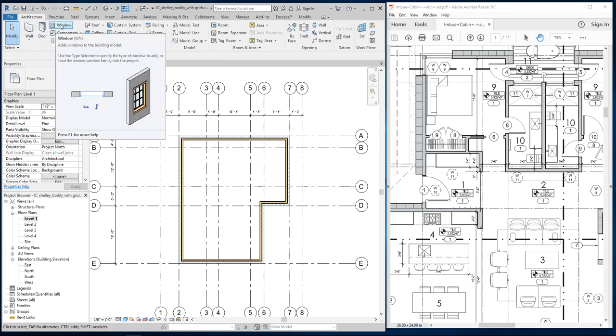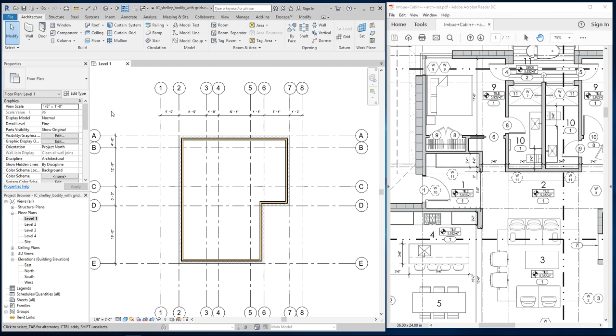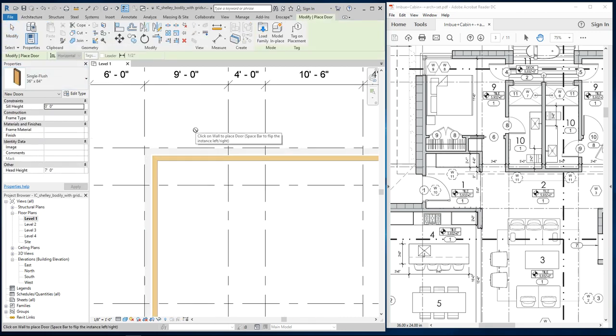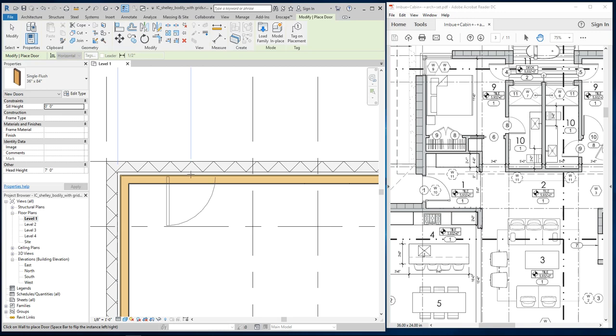It's WN, okay? So when I want to add a door, you guys who've been using AutoCAD, you're just going to die over this, right? To add a door, I click on door, and I hover over the floor plan where I want the door to go, right? Click. Look how easy that is. I know, right? Nice and cleaned up. It creates the opening. It shows the panel. It shows the swing. We don't have to use arc anymore, right? Which is wonderful. I know, my nemesis, the arc.